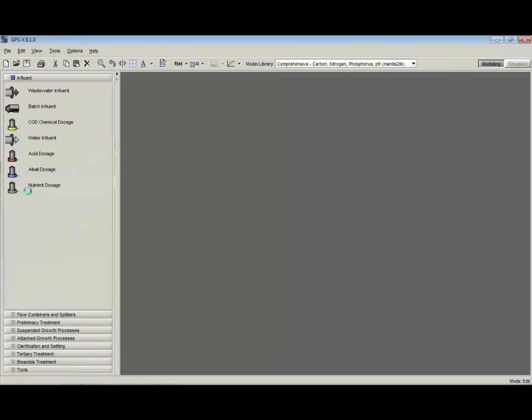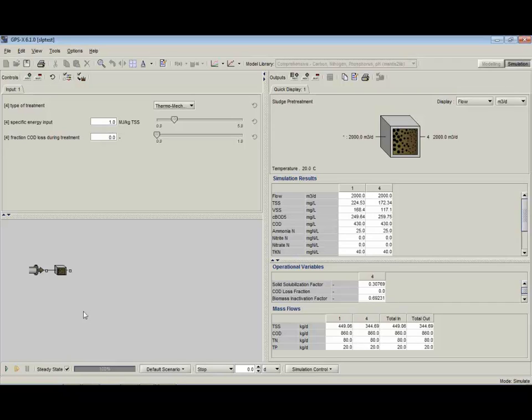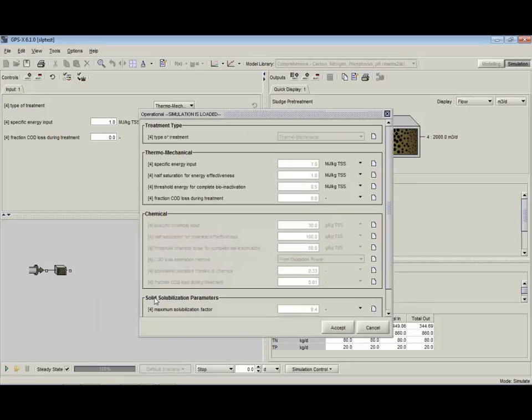Just to show you what the new object looks like, it's this one here. Because we were describing many different types of processes, we made a generic object that shows large particles being broken down into small particles. The idea is that you have some sort of COD coming in one form, and then we break that down. You can notice here that we're having a decrease in the VSS as it goes across. We're breaking down some of those solids, and the readily biodegradable soluble BOD is going up. So it all mass balances nicely, and it is a relatively efficient model. It's a bit of an empirical thing, but we've had some pretty good success with it.